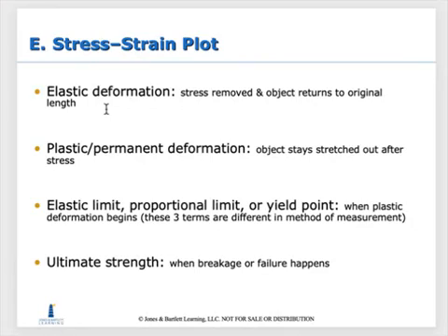There's an elastic deformation. This is when the stress is removed, and whatever that material is, it can go back to its original length. So think of that spring. Once you take that weight off that spring, it's able to go back to its original length, hopefully. Plastic or permanent deformation. This is, let's say that same spring, we keep putting weight and weight and weight on, and we leave it on there.